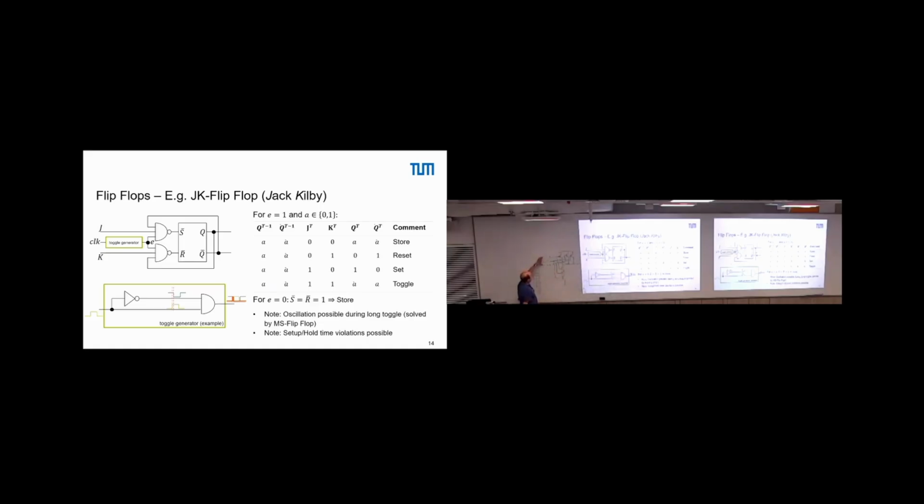So, if one of the three inputs becomes a 0, then we connect to VDD here, and we disconnect from ground here. Only if all of them are 1, we connect to ground and disconnect from VDD, right? Yes. So it's nothing else than switches at the end. So in CMOS technology, the transistors are nothing else than switches.